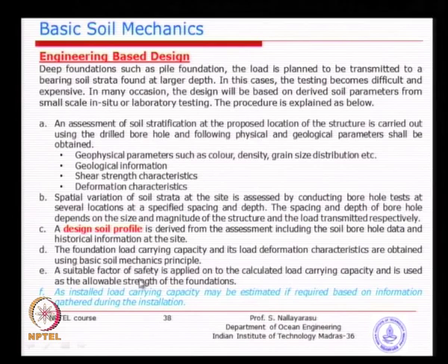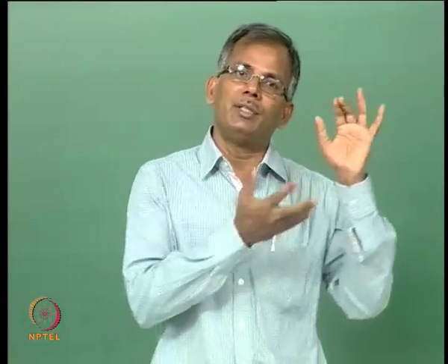And for different types of piles and foundations, varying factors of safety are recommended by code experts, but for steel pipe piles for offshore applications, API recommends a minimum factor of 2. That means, you calculate the capacity as 100 tons at ultimate failure, divide by 2, and that will be the load the foundation can take safely without excessive deformation. So, basically a factor of safety of a minimum of 2 is required.